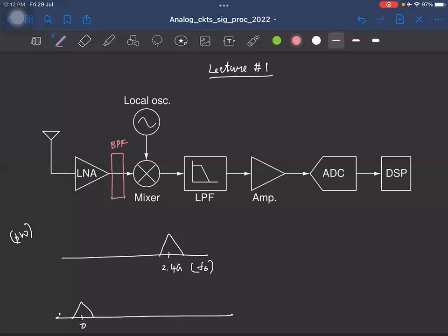And it's highly probable that those signals are also located very close to each other, right? So the job of your receiver is to only look at this small desired signal and reject all the other neighboring channels, right? So essentially you need a bandpass filter.